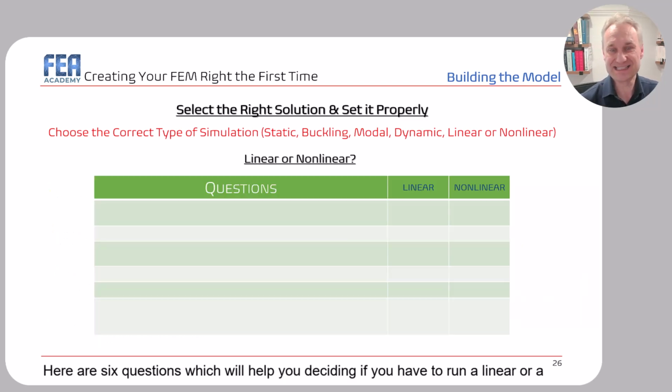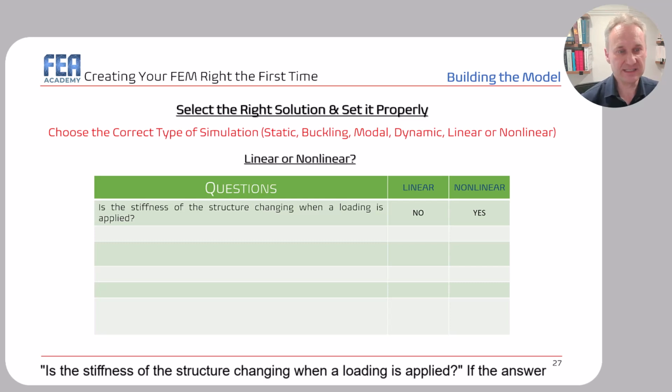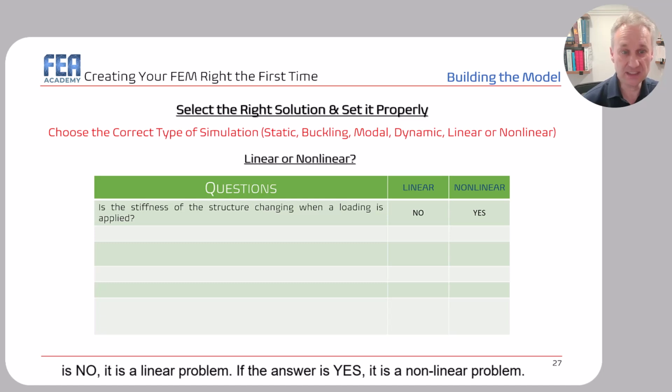Here are 6 questions which will help you decide if you have to run a linear or a nonlinear analysis. The first question: is the stiffness of the structure changing when a loading is applied? If the answer is no, it is a linear problem. If the answer is yes, it is a nonlinear problem.